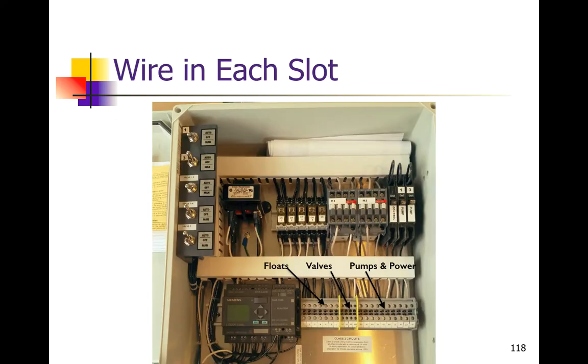So the first thing we want to look at is the control panel. You don't necessarily have to know the wiring diagram sequences. What is important to know is when you first look at the control panel before you turn the power on, look at the bus terminal and make sure that you've got a wire in every single position that's in here. It's very important. If there's wires missing, you might want to make a call. There's some reasons potentially that some wires could be missing. If a wire is missing, it may be something was just left out, and we need to identify that.